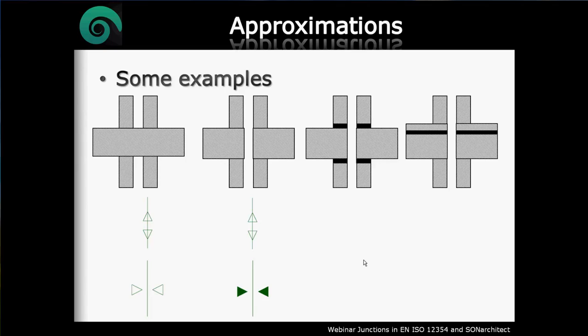If we insert elastic interlayers on top and the bottom of the walls, which is exactly the same case that we have seen before in the right part of the slide, we will find that besides the interruption in the slab, we also have an elastic layer going from the slab to the flanking path that goes up to the wall. And this can also be modeled through an elastic interlayer on top and bottom of the wall.